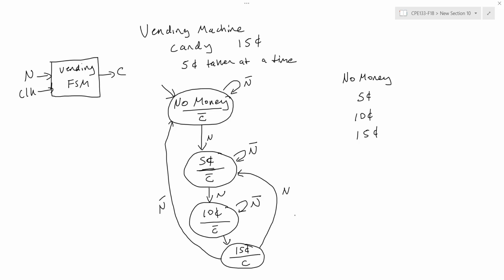And this particular FSM, I built this with a single Moore style output. Now note that because the output only depends on the state, which is the case for the Moore FSM output, we can go ahead and write the output inside the circle itself. This is as opposed to a Mealy finite state machine output, which we list on the edges, because it depends both on the current state, the circle that I'm in, as well as the input, which is listed on the edge of this graph.